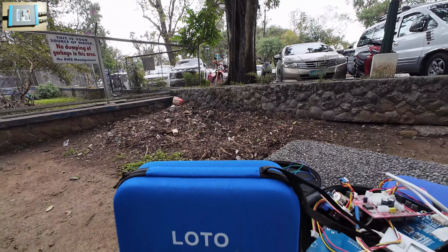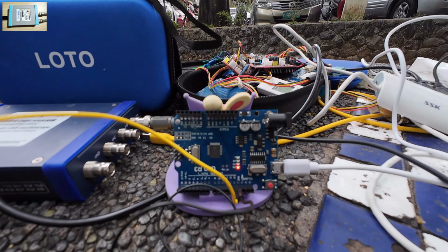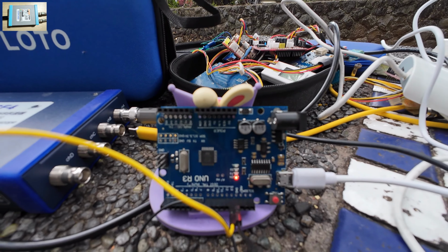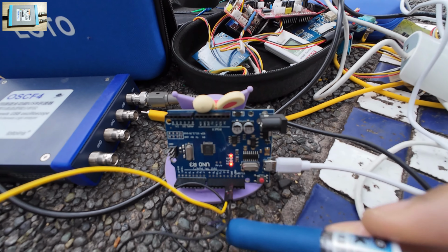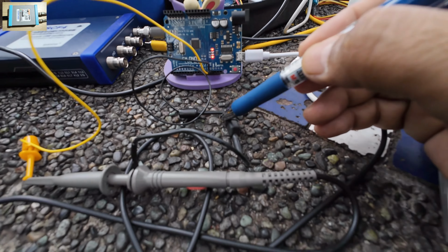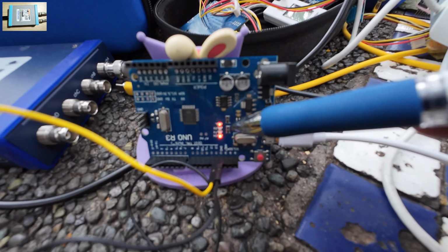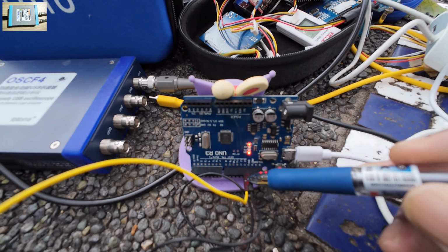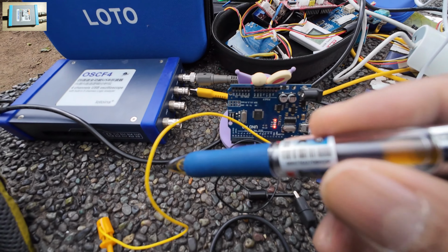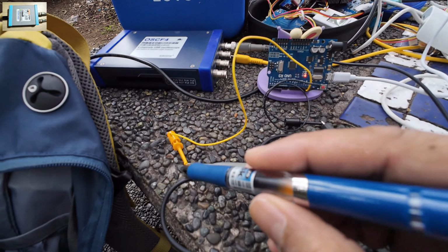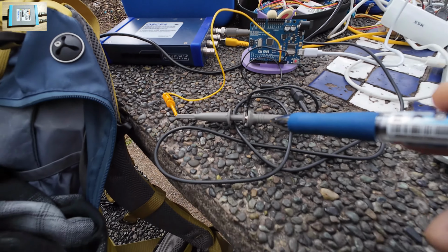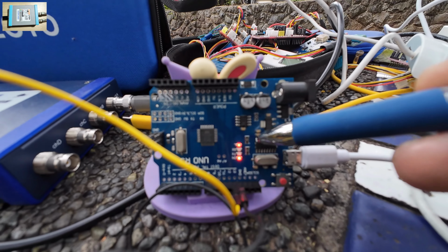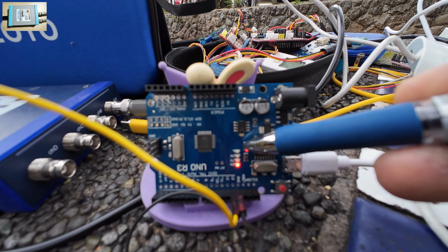That's her business. So going back in here, this is the Arduino Uno. And you can see in here, this is the GND. And this is the black connected to the ground of the oscilloscope. And this is the pin in here. The pin is just over there, and it is connected to the yellow cable and connected to the positive of the oscilloscope, and then input to channel A. So this is the pin. It is blinking at 1 second.